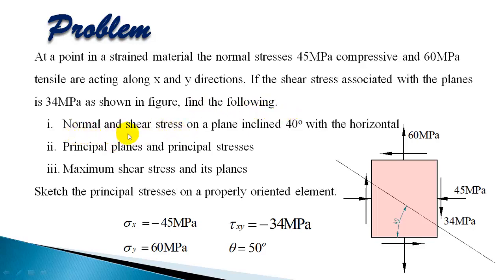First, normal and shear stress on a plane inclined 40 degree with the horizontal. Second, principal planes and principal stresses. And third part, maximum shear stress and its planes. Sketch the principal stresses on a properly oriented element.